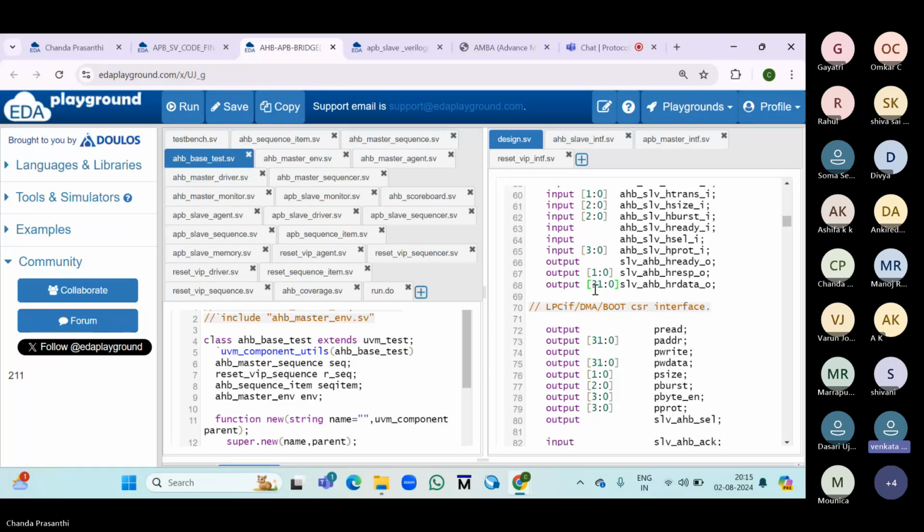Depending upon the scenarios, what we are facing, we need to develop the thing. Depending on the availability, we can take. We don't have any fixed master and fixed slave. We can use anyone because all are bidirectional. We cannot say every time the processor will be the master and some memory will be the slave. The transaction will be done from master to memory and from memory to processor also, vice versa. It totally depends on the specification.